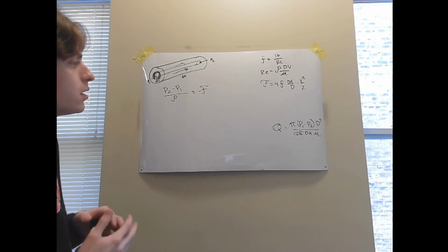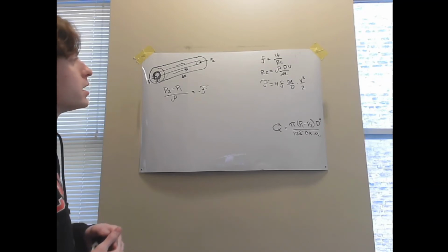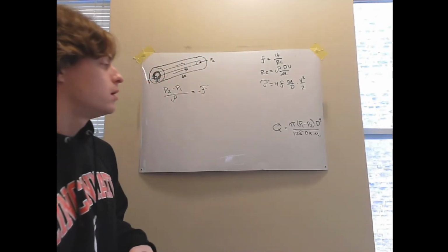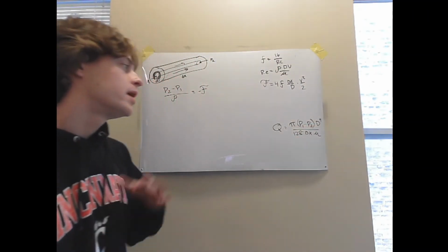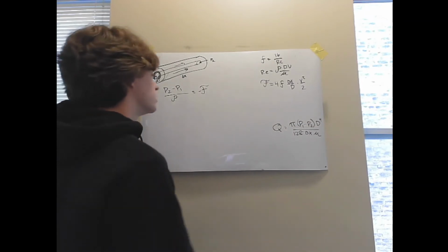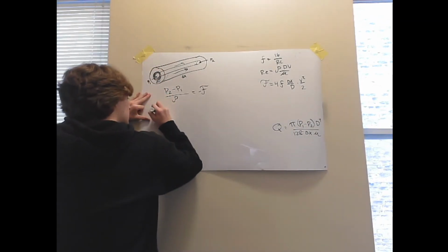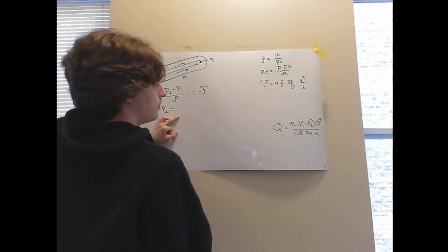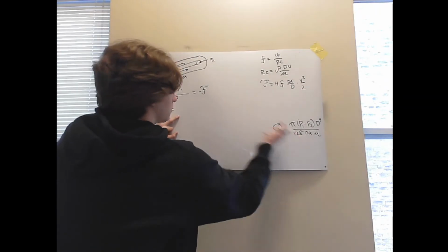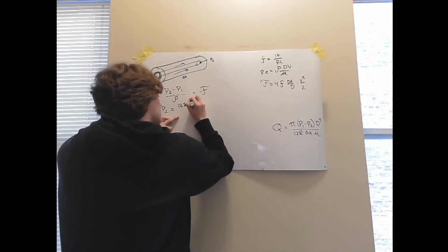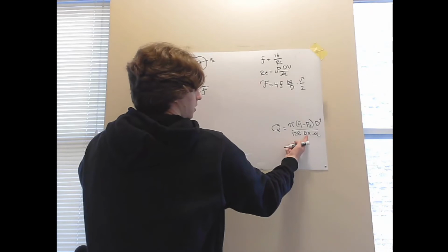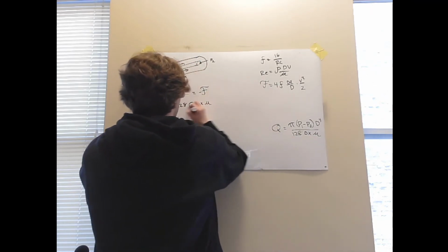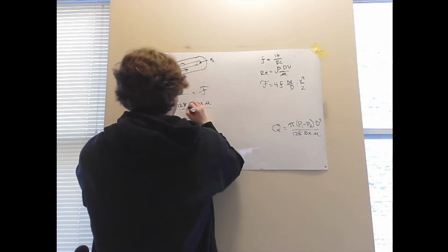So now we can go ahead and plug in. We can rearrange our equation for the volumetric flow for P1 minus P2, and then we'll be able to plug it into our Bernoulli's equation. So just solving for these, we're going to multiply by 128, we have Q multiplied by delta X and mu, and then divide by pi and d to the fourth.